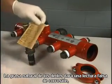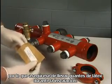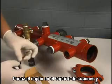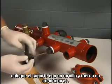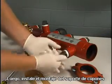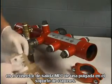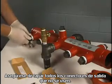Oil from your fingers will provide false corrosion readings, so be sure to wear latex gloves during the installation. Assemble the coupon on the coupon holder and attach the holder with a non-conductive screw and nut. Next, install the coupon holder assembly in the 1-inch NPT outlet fitting on the coupon rack. Be sure to plug all outlet fittings that are not being used.